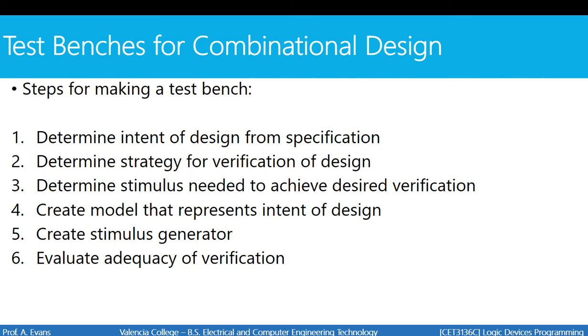So the steps for making a test bench, we start by determining the intent of the design from a specification. So for example, today would be what's the intent of a half adder? It has 2 inputs, it has 2 outputs, and it provides the binary sum and carry based upon the 2 inputs being added together. So that's our specification. Then you determine a strategy. How am I going to verify that the half adder works correctly? You have to determine the stimulus needed to achieve your desired verification. In our case, we need to make sure that we can simulate all 4 input scenarios for our 2 input half adder and verify that the outputs are correct for each set of inputs.